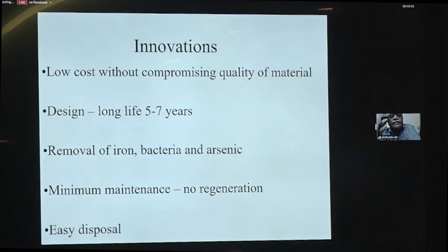So what are the innovations in this filter? The innovation of the filter is it's low cost without compromising the quality. It has a long life, 5 to 7 years. During this life period, there is no maintenance. You need not regenerate the media. At one shot, it removes iron, bacteria, and arsenic, and the disposal is easy because the spent material does not leach out arsenic, so it can be used for road laying purposes after its life is over, after 7 years.